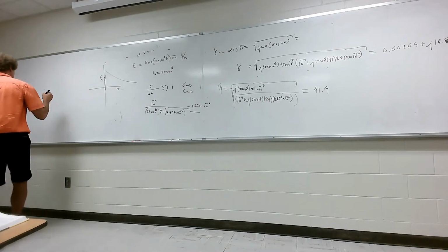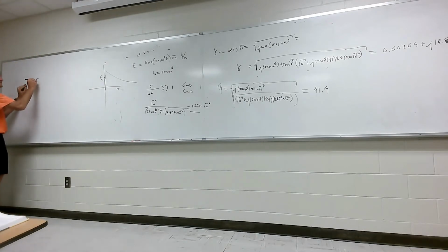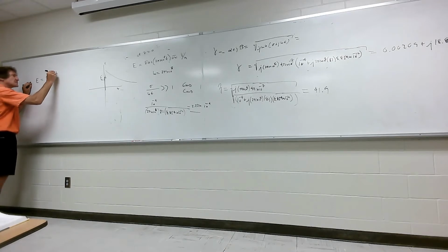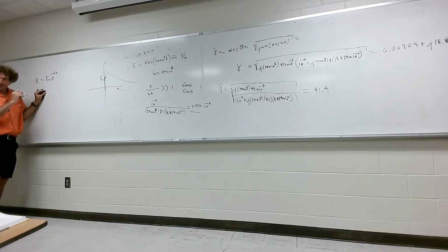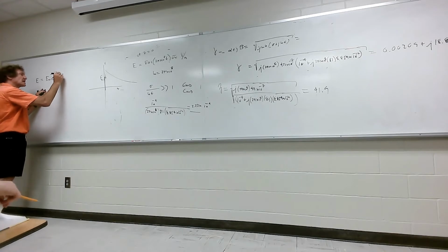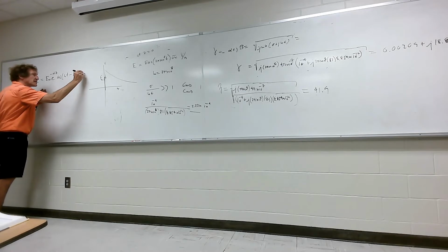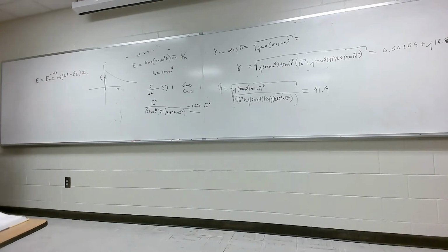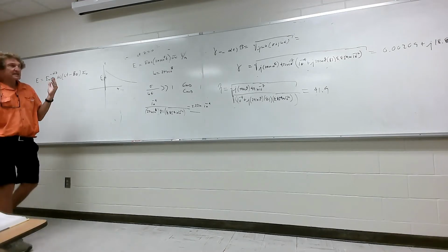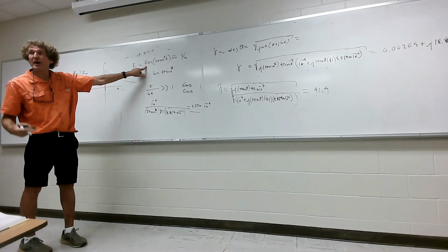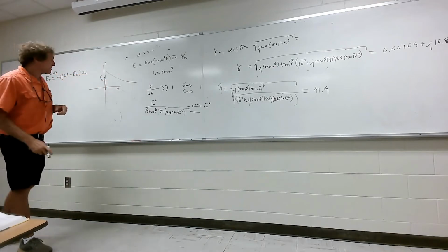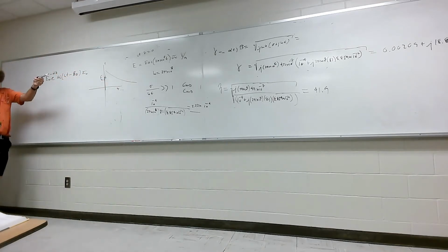So now we can say, in general, the E field has to have the form of some E naught, e to the minus alpha z. Just remember that has to be there. Then it's going to be times cosine of omega t minus beta z in the ax direction. That's the general form we're going to fit it for in the time domain. Y'all with me? Now, he says when it's at 0, it's this. So we already know 8 is the coefficient, the magnitude. Y'all follow me on this, class? He gives us that, so I can just make this 8.